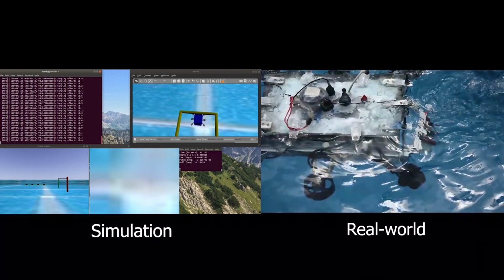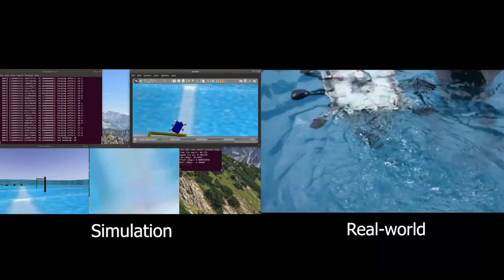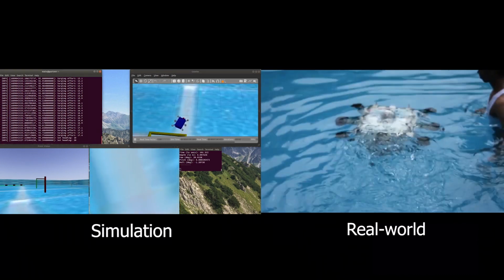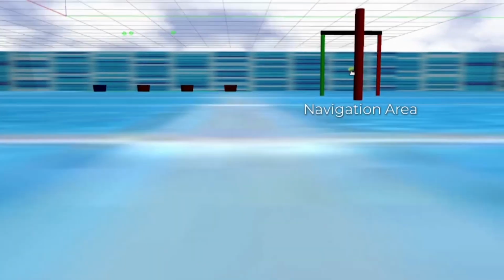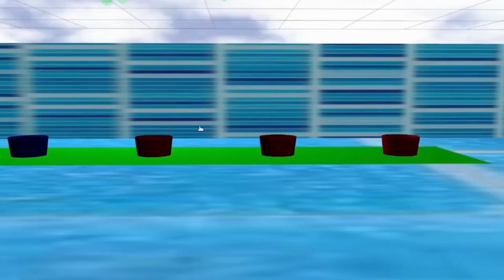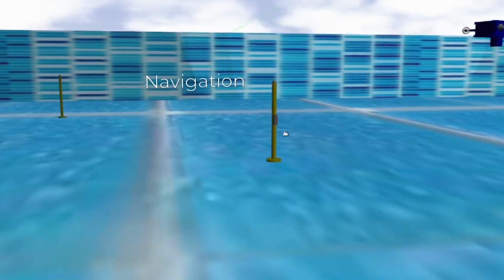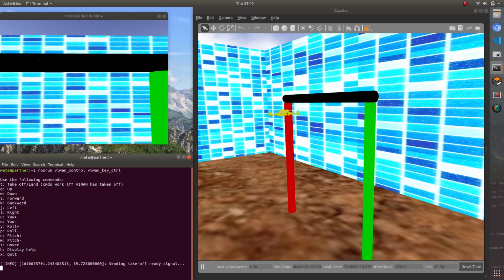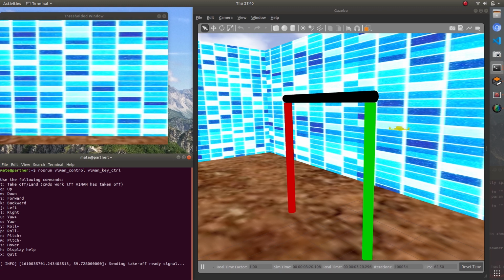Let's take a look at how the AUV society has been using ROS. We have developed the control algorithm of our vehicle using ROS. We execute the same code for testing our vehicle in both simulation and real world. Using an allied tool called Gazebo, we have developed a complete testbed for SAUVC. Apart from underwater simulation and testing, motion of aerial vehicles can also be visualized.